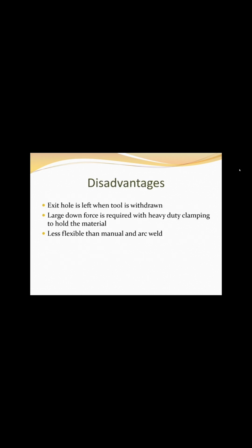And coming to the disadvantages: an exit hole is left when the tool is withdrawn. A large down force is required with heavy duty clamping to hold the material. Less flexible than manual and arc welding.